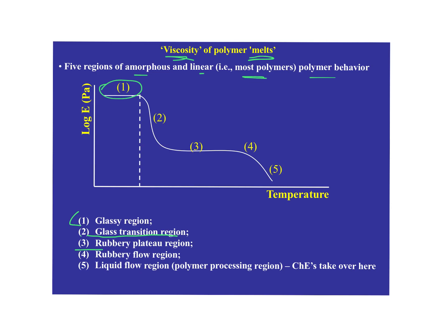The majority of what we work with, though, involves the rubbery plateau region, so this region here, which is above the Tg, and then the rubbery flow region, and then a lot of what we're talking about really involves the liquid flow region. And this is where the chemical engineers take over, typically, where they describe all of these fluids, all of these different bonding circumstances, as this gray continuum with no real discernible characteristics. They just say it has this rheology, and then we go to town with rheology. Anyway, so that's a lot of what we're talking about, because this is where we start to make things.